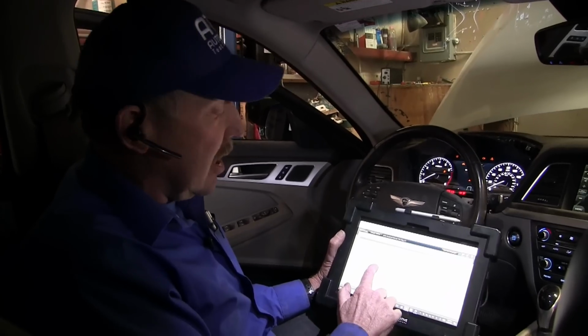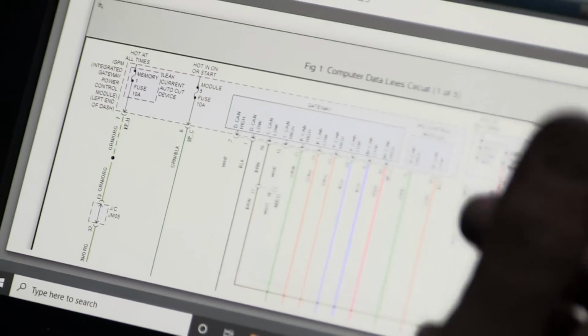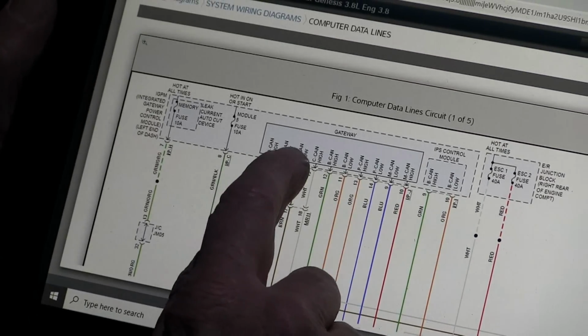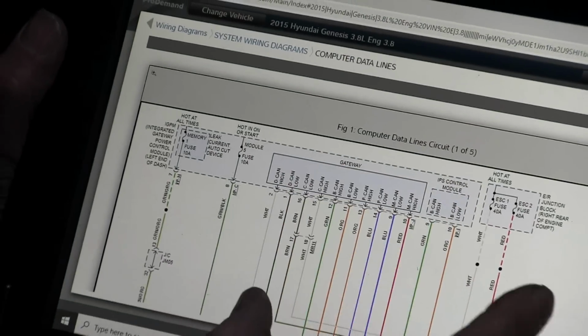Now Ford deems that that's okay, but other manufacturers want to isolate the DLC from any of the bus structures, and you do that by diagnostics on CAN or DCAN. The diagnostics on CAN will only go in to the gateway. It doesn't go out of the gateway. And then we have all of our other systems that are also operating through the gateway or the bridge.